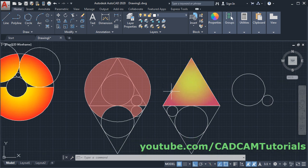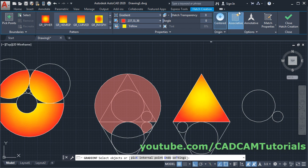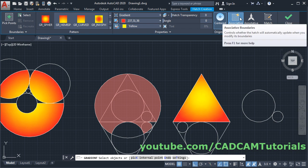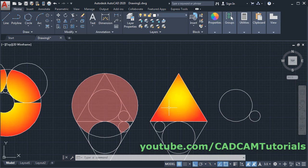And these hatches have been created as associative. If you click on this hatch, you can see here the associative option. It is on by default. Therefore, whatever hatches you create, those are associative. Now what happens because of this associative? Press escape. If you change the shape, your hatch pattern will also change.